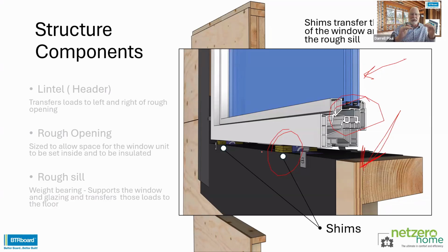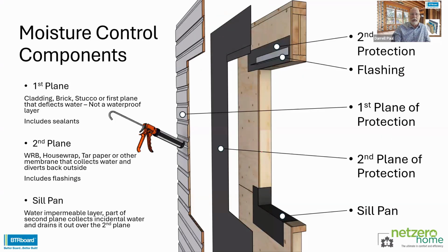My preference is that those blocks, those supports should be structural. They should be water resistant or not damaged by water. You can see that these are preserved wood here. You could use a plastic one, whatever. And that's supporting that so that it doesn't crush and you lose the seal on the window. So now you're not just dealing with water coming in through the rough opening, you're dealing with water coming in through the window.